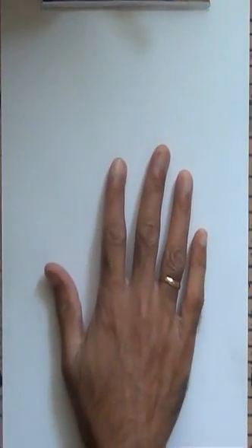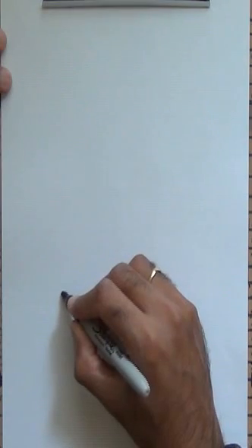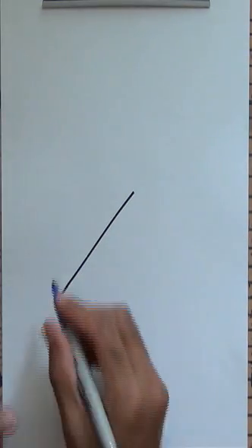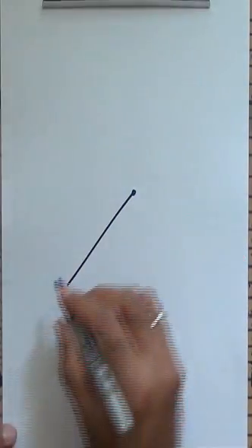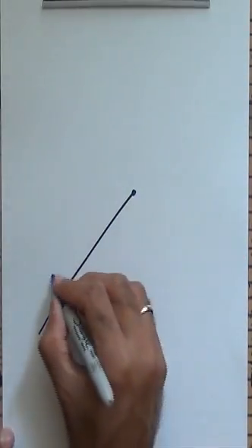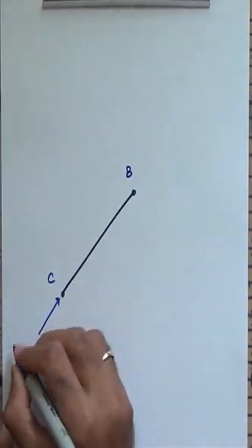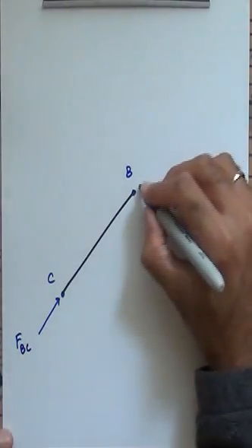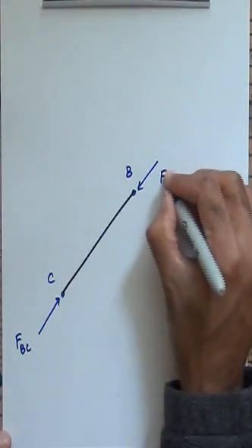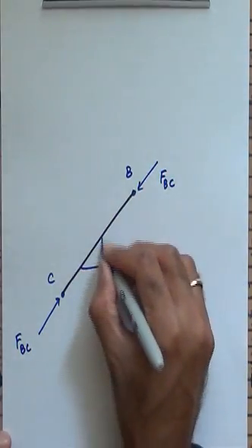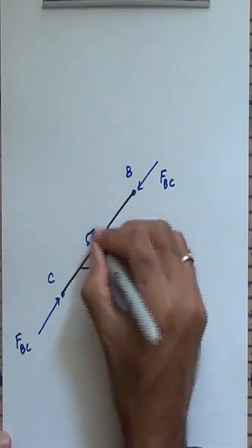Alright, so since that is the case for us, I'm now going to redraw the free body diagrams of ABD, knowing that I have recalibrated the free body diagram of BC. So you see, if I look at BC, there were forces at the point C and at the point B. So this was C, this was B, this was FBC, and I know that this force was also FBC. Slope triangle was 3, 4 and 5.